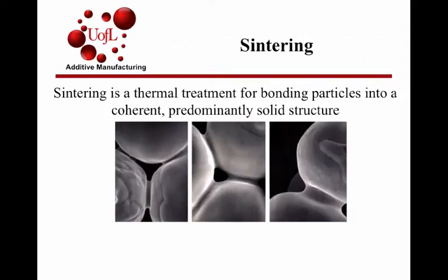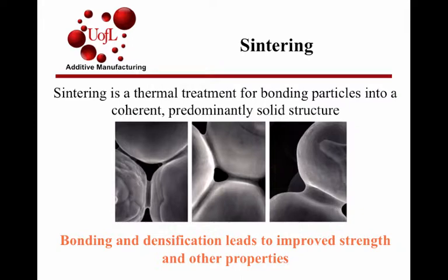We looked at sintering as a common route traditionally used for fabricating dense components out of powder metals. Sintering approaches are used after shape creation for a few 3D printing technologies such as selective laser sintering, fused filament fabrication of metal polymer composites, photolithography applications using metal powders, and binder jetting. So in sintering, you're really talking about a thermal treatment, as we reviewed, to bond particles, improve strength, create densification, and improve other properties as well.